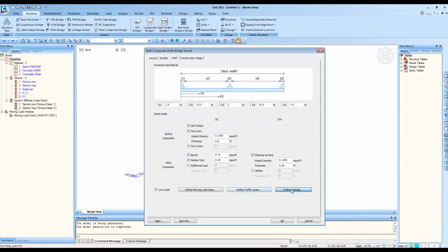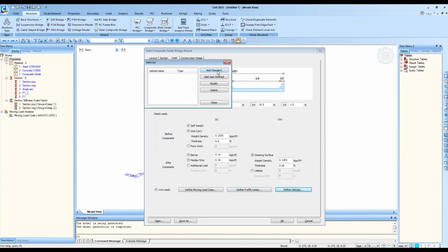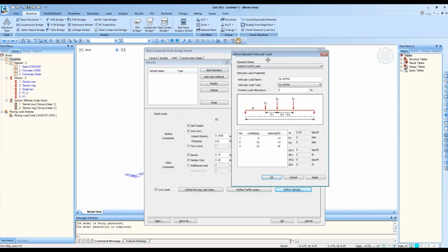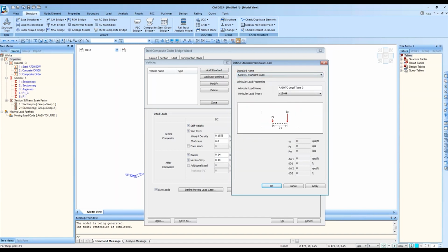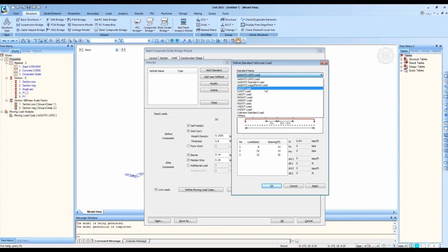But one more thing to mention. In MIDAS, we actually implemented a lot of DOT vehicles. If you haven't upgraded your program, in the 2015 V 2.1 and 2.2, you should be able to see a list of the vehicles. And besides the AASHTO LRFD, and the old standard load and the legal and permit trucks, you will also see the DOT loadings. So please take advantage of this load database.